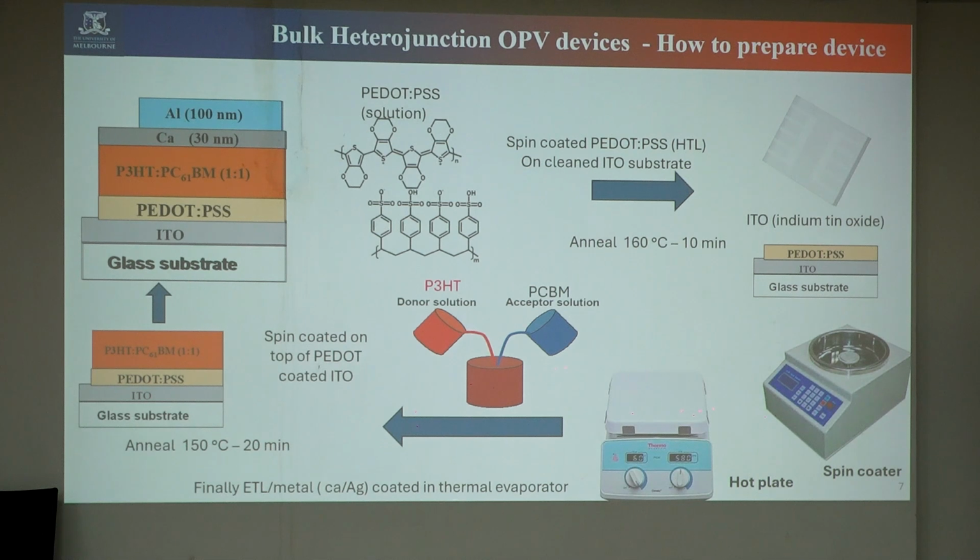I'm going to talk about what we are doing in interface engineering for this layer. We can either evaporate aluminum, or alternatively use silver paste, which we can also print for the final purpose. But at laboratory scale we want to get the best out of it, that's why we do all of this in thermal evaporation conditions. So this is a normal full fabrication process, though some things may be different. Basically we need one hole transport layer, one electron transport layer, one transparent electrode and a top metal electrode. So these five layers are essential for any device to work.